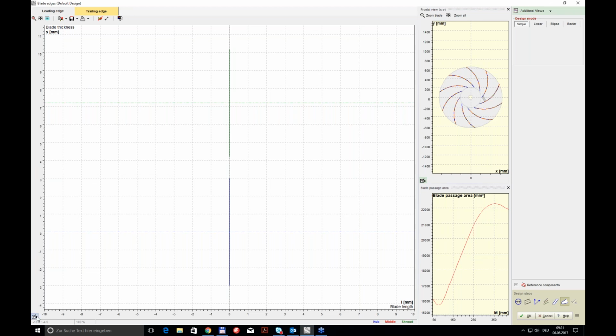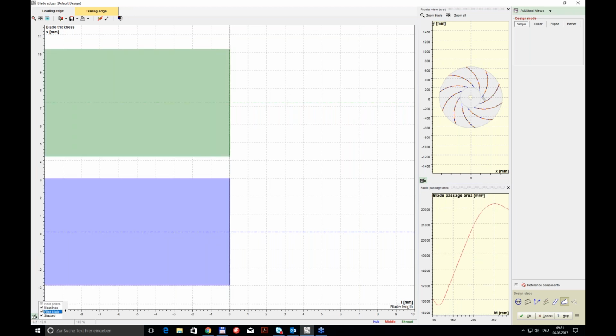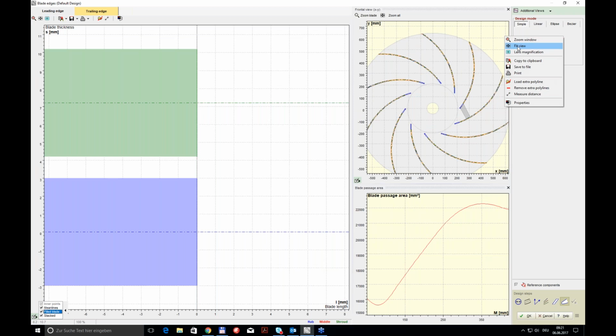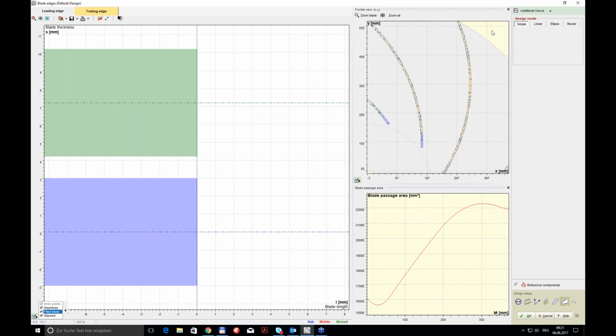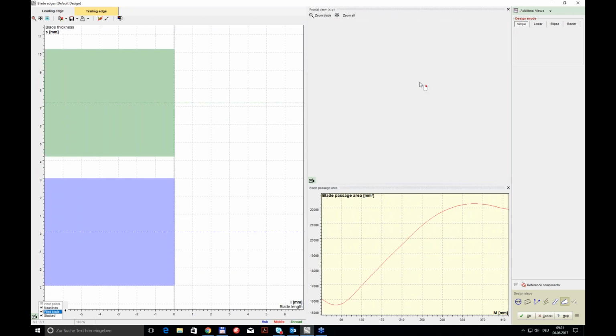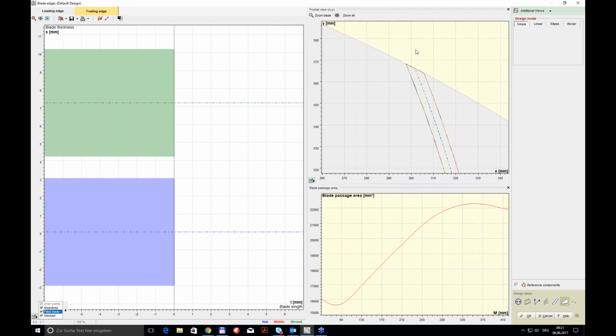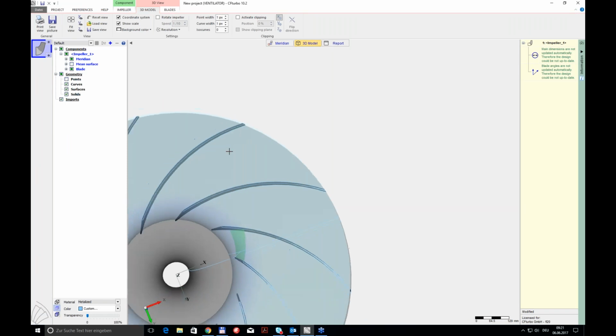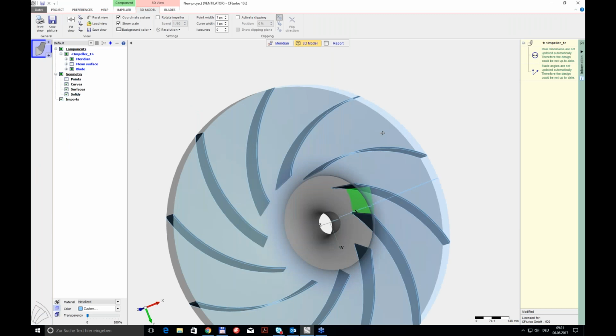On the other hand, at the trailing edge, one wants to have it trimmed with the outlet, and that's why this simple mode is applied here, and you can see that here in that frontal view that now the trailing edge is not looking out of the meridional contour anymore. Okay, now if I go to the 3D model, it's done.